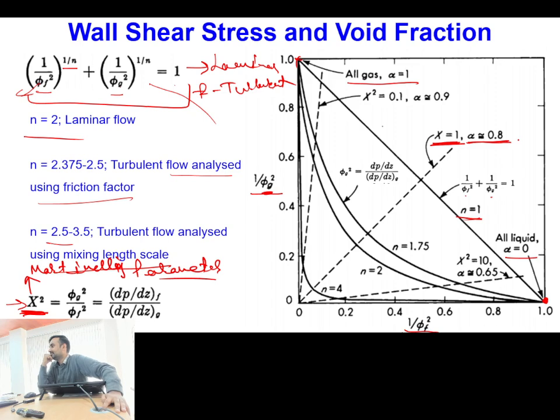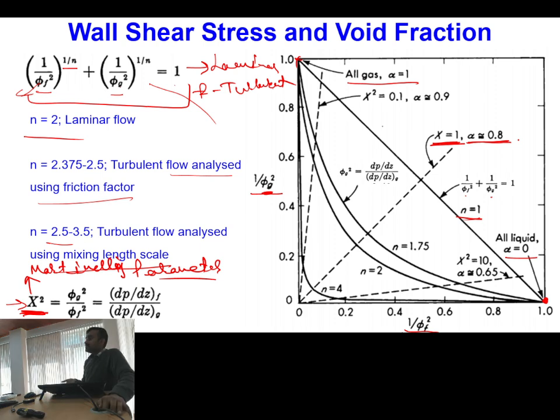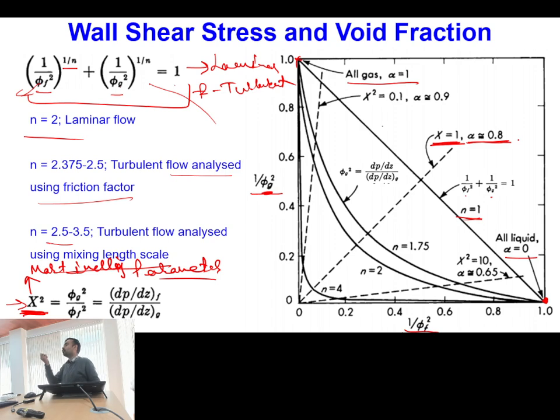This is because here we are considering the volume quality, and the gaseous phase will be having low density. Okay, so because of this it will be occupying more area. So corresponding to that I will be having some asymmetry in pipe size and the amount occupied by the gaseous phase. Okay, so because of this we will be finding that x equal to 1 is giving me a very high value of the volume fraction of the gas.